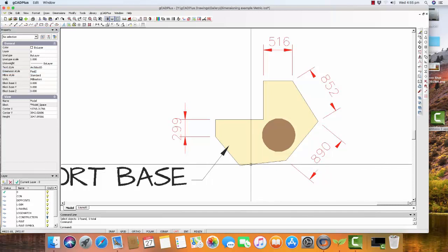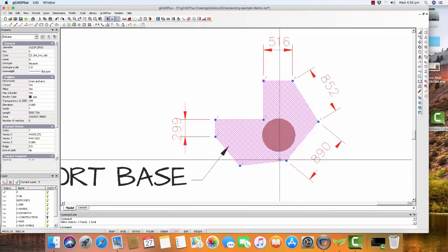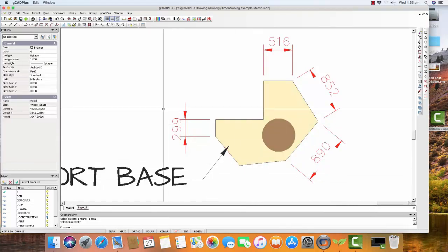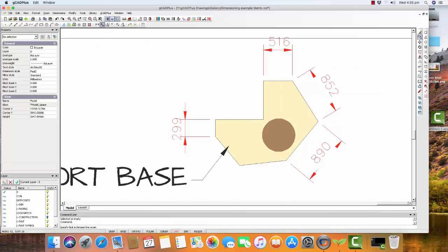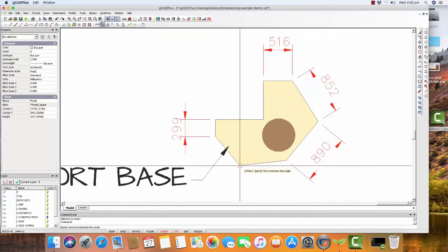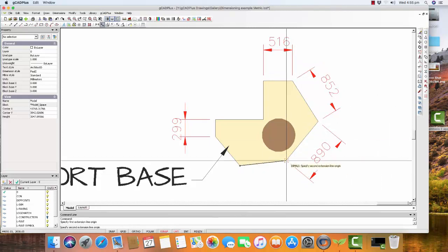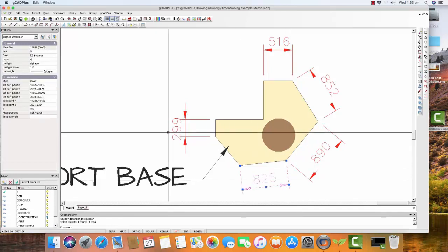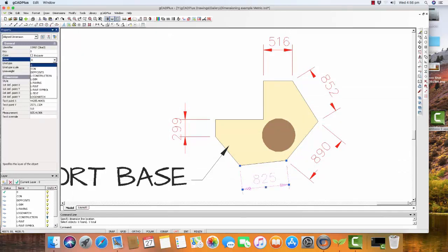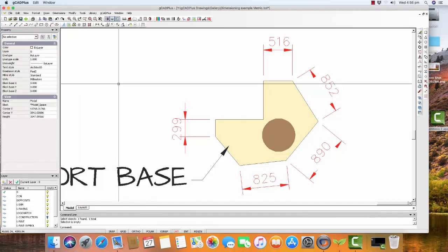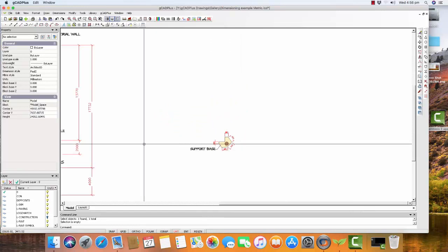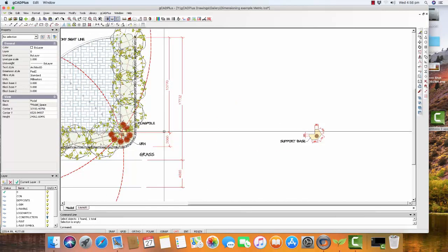And the angle, if I select this polyline, the line I want to dimension now clearly is at an angle. And to dimension that, we use an angular dimension, which is this one here. Angular dimension, we pick the end there, and for the other termination of the line, we go there, and I'll select that dimension and put it on the layer LDIM, and its colour, of course, will change to red. So we dimension this area using one dimension style and the main design area using another.